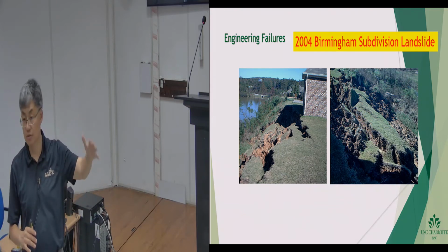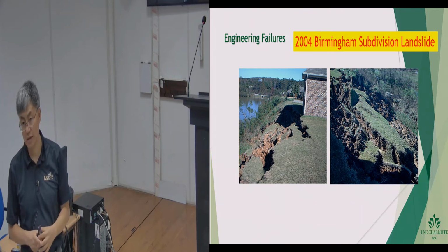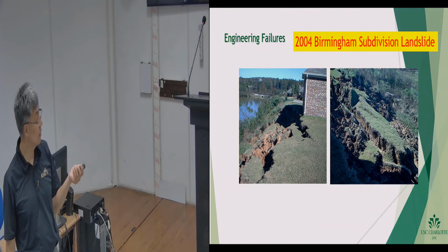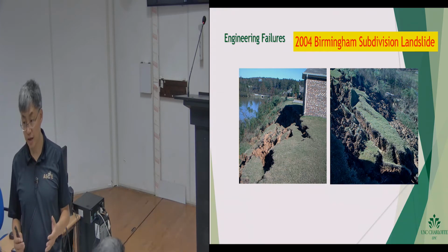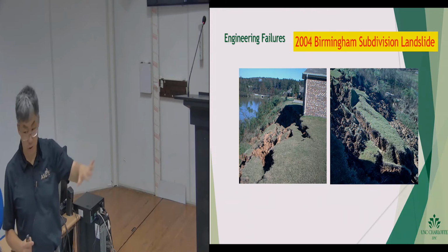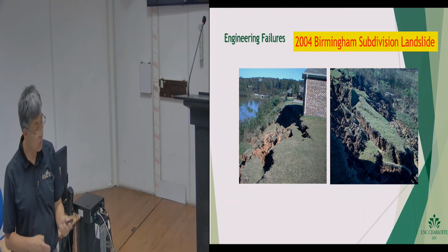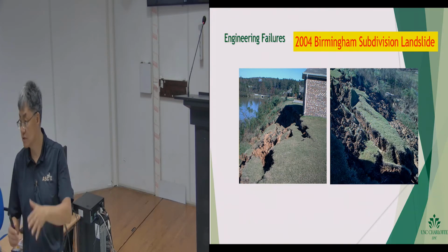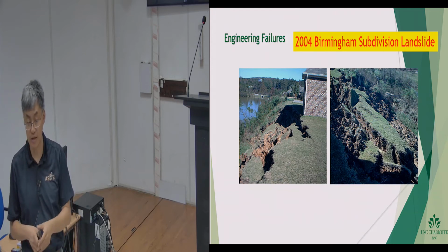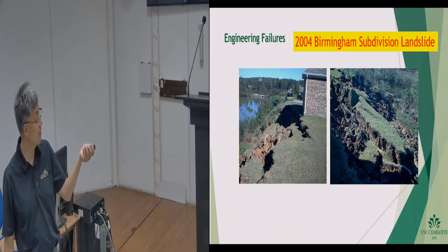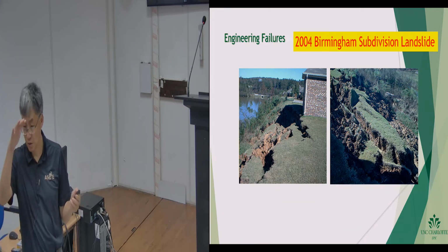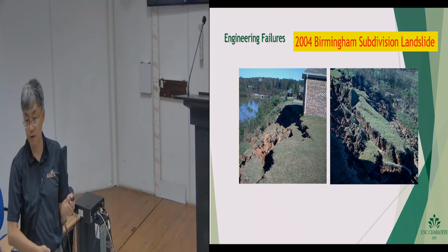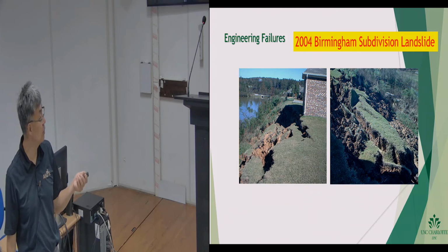Birmingham has a lot of small hills, not mountains, more like Madurai. But the problem with Birmingham is when people start building a lot of homes, it actually changed the groundwater level. When you have poor compaction of a home, suddenly the groundwater drops, then you start having soil collapse. We see a lot of those homes having slope failures or soil collapse compounded failures, and we have to go and do investigation.